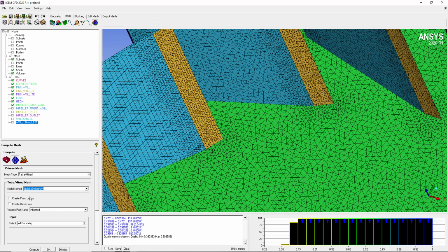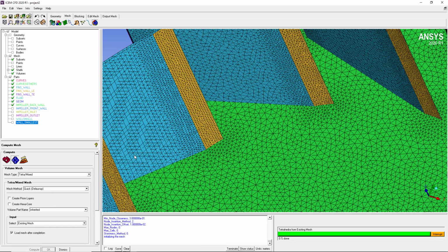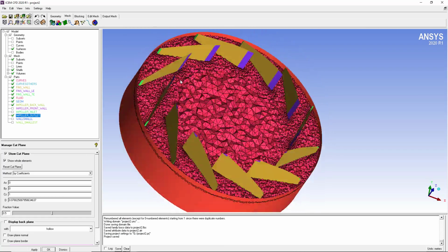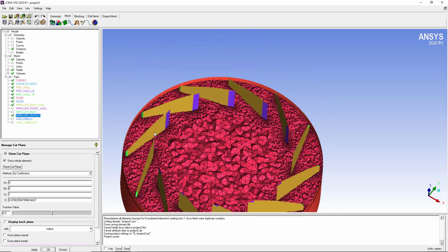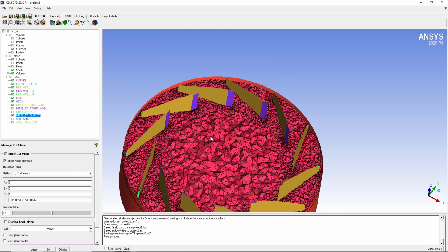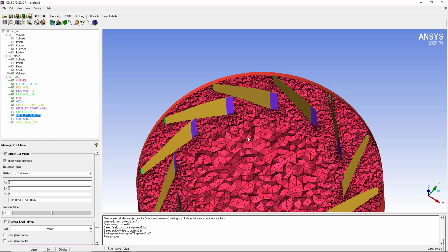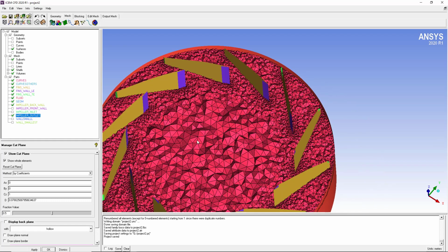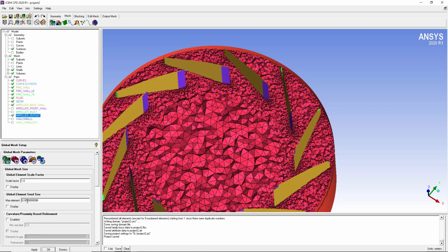and this time we use the quick Delaunay method. The benefit of the quick Delaunay method is that it will create the volume mesh with a very fine quality. Now you can see the volume mesh after the Delaunay method, and the transition between elements is very controlled. We have refinement near the surfaces, and as we go into free space, the elements increase, and the maximum size we will get is equal to the element size we defined here, which is the maximum element seed size.